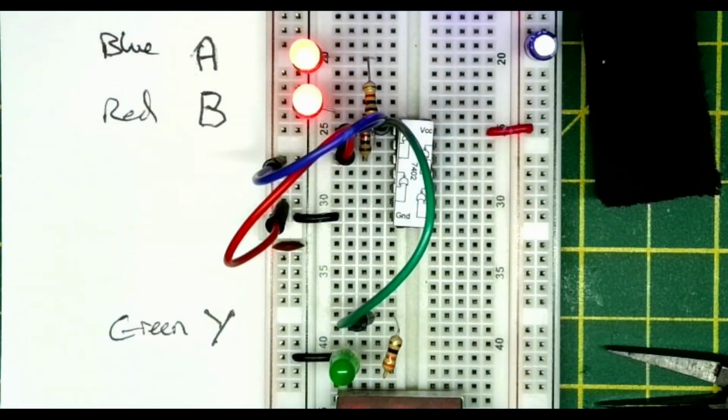Now again, the NOR gate is a useful gate in that we can also make any other gate with a NOR gate. So both the NAND and the NOR gate allow us actually to create any other gate from them. It won't necessarily be the most efficient way of doing it, but it certainly allows us, if we had spare gates on a NAND or a NOR gate, we wouldn't necessarily have to add another chip. We could make up some of the other gates with the unused NAND and NOR gates.